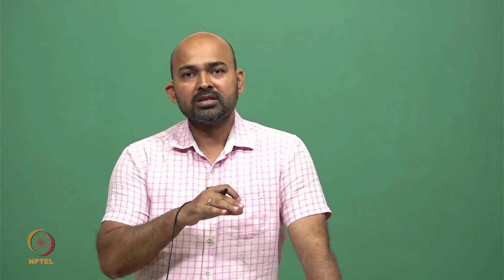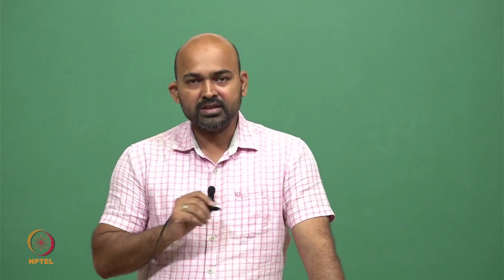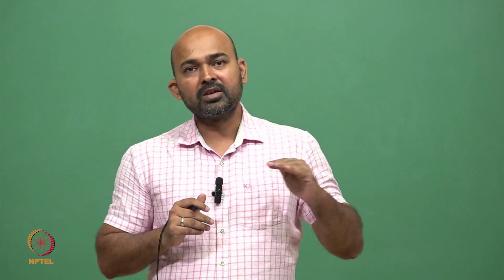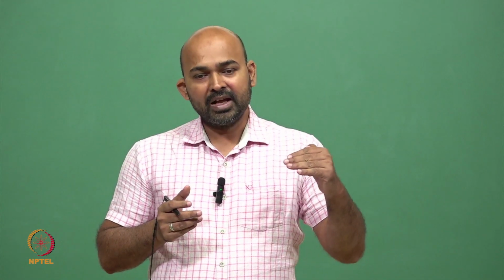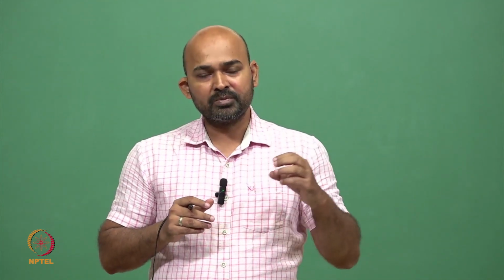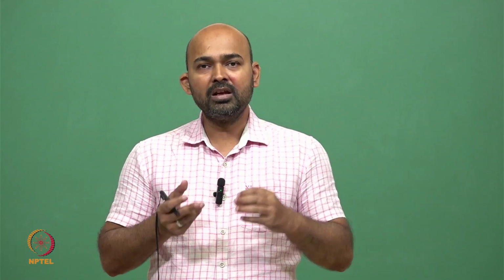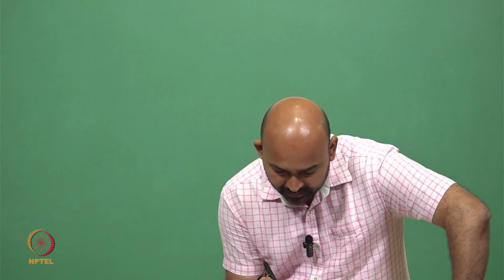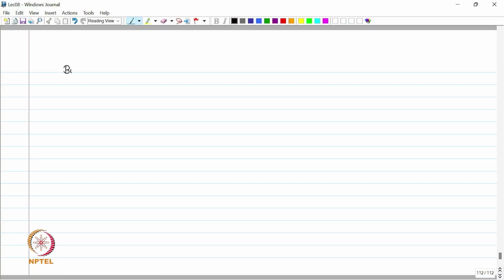Now we discussed the SAW sensor, which is the surface acoustic wave sensor. In all these cases, the wave is actually traveling on the surface of the piezoelectric material. Let's discuss something called the BAW sensor, or the bulk acoustic wave sensor, where the wave will actually penetrate into the material, it will pass through the material, not on the surface but into the bulk. That's why we call it the bulk acoustic wave sensor.